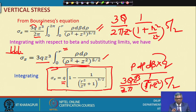So, by this integration, what I have got is, when a load is applied through a circular footing, along the central line vertically below the footing, what the stress intensity is. That gives you this expression, but not at any other point. At any other point the intensity will obviously be less, and we can also find it out, but there is some complication in the method, so I am not discussing it right now. Later on we will discuss that. Right now, whatever we have got is at any vertical depth through the center of the footing, and that is critical.